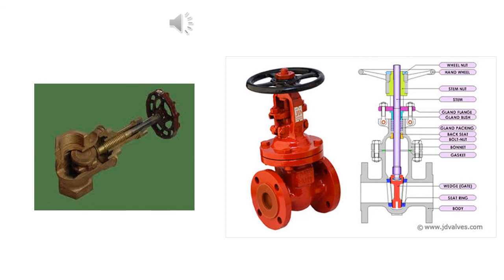On opening the gate valve, the flow rate does not change evenly with stem travel. Also, a partially open gate disc tends to vibrate from the fluid flow. Most of the flow change occurs near shutoff, with a relatively high fluid velocity causing disc and seat wear and eventual leakage when the valve is closed. Typical gate valves are designed to be fully opened or closed.